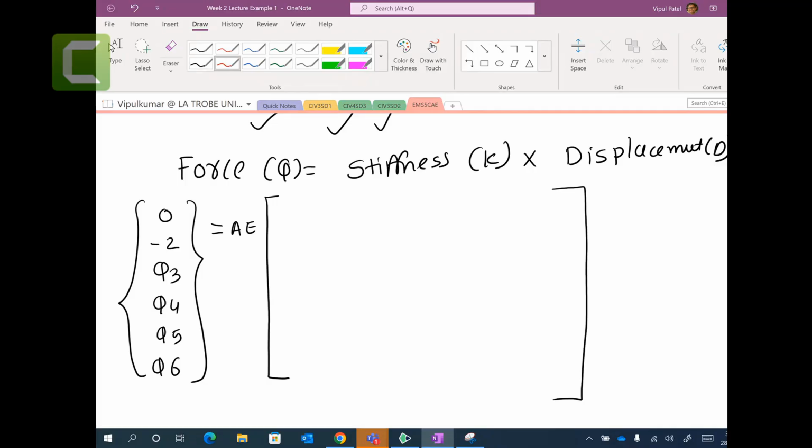Now, before we use the stiffness matrix, I'd like to do the partition of the matrix. Partitioning means that you have a complete border line in this matrix. You can see 0 and -2, and after that you have Q3, Q4, Q5, Q6 starting. So you have 1, 2, 3, 4, 5, and 6, and you can see the partition here. If Q3 is not there, if Q3 is some value, you can have the partition line from 3. So you can see clearly the partition line at 2.